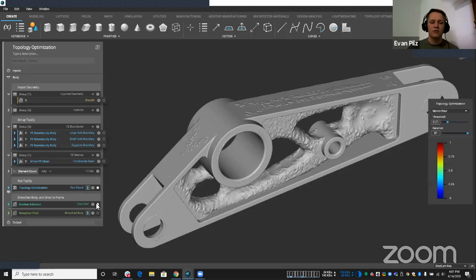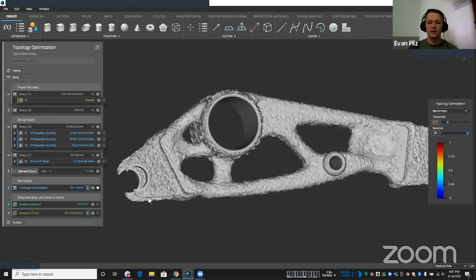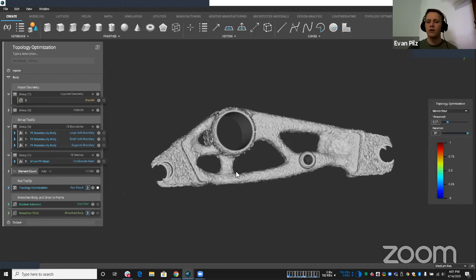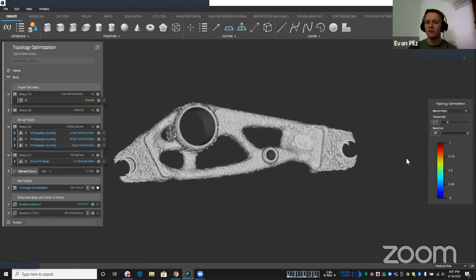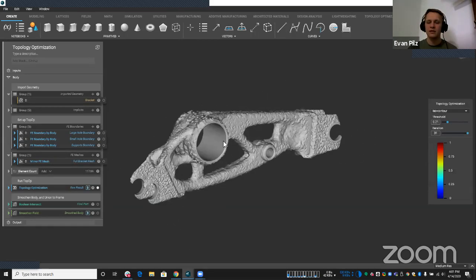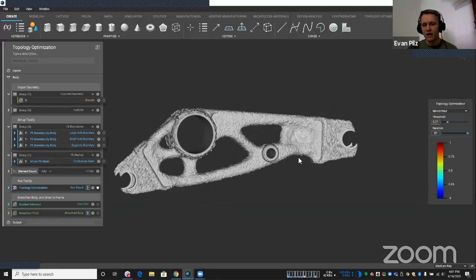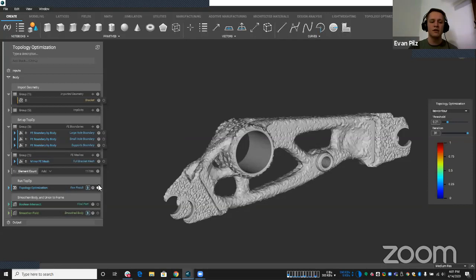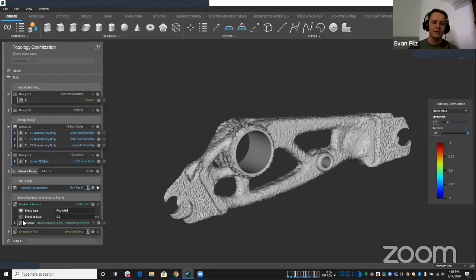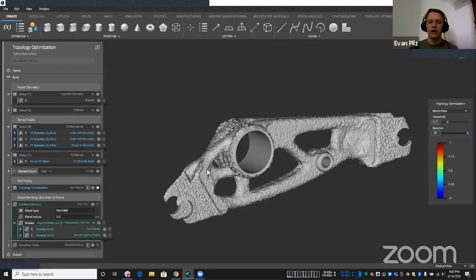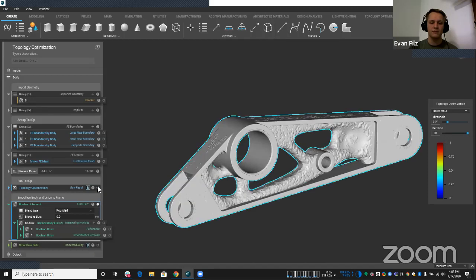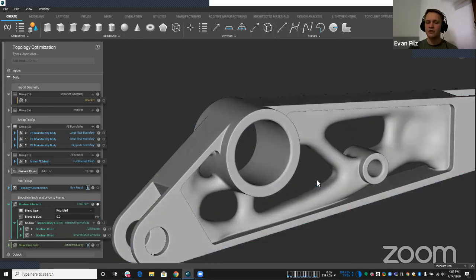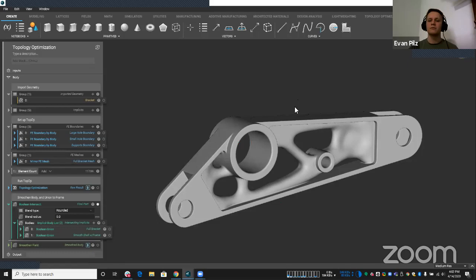You can see if we go back to our raw result here, we're missing some stuff. These mounting holes aren't closed. There's a couple other sharp edges and pieces that are missing. And that nice frame that we had is gone. Why didn't I make that all passive? Because inside of nTop, you'll see here, it's one operation where I turned this into an implicit, smoothed it, and then used a Boolean union and put our nice smooth geometry back with that geometry we wanted to keep.